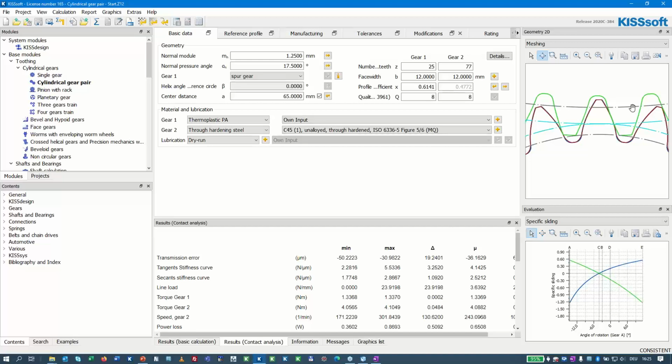Let me answer the second question. The DIN quality grade that can practically be achieved: the best companies we know are at grade 5. That's quite tough. So DIN 5, we know companies who can do it, but that's not common.